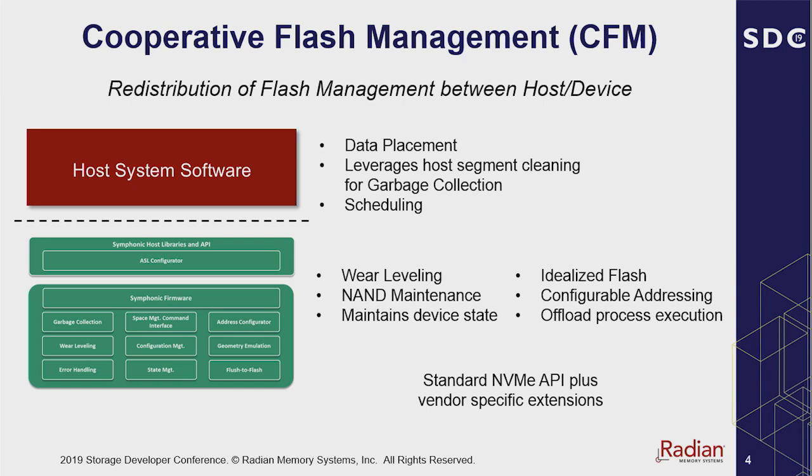Symphonic was the first implementation in the industry to partition these flash management functions in this manner, where the data placement, control of garbage collection, and scheduling of maintenance operations reside on the host, and NAND maintenance resides on the device. Device responsibilities also included state management, options for configurable addressing, and a zero-copy offload feature to reduce host resource consumption and improve scalability.